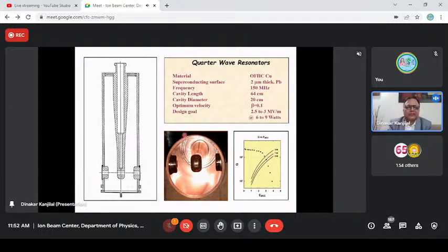Only Argonne National Lab had it. And though we collaborated with them, there is no plating possible. So one has to have pure niobium, and then electron beam welding, an all-automated robotic process, one has to follow to make this cavity.